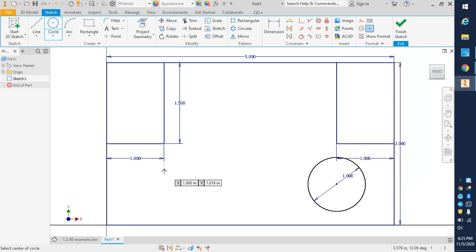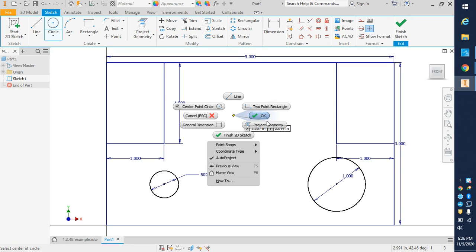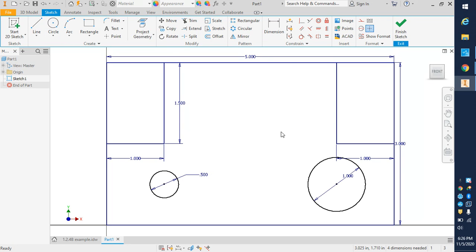All right, we're going to make one more over here. I want to share the same center as this one and this point, so I'll drag those down. Where those inferred points intersect, we can go ahead and click, move my mouse, and we're going to go 0.5 for the size of my circle there. And just like that, we are about done. Right click, OK, turns off my drawing tool. I'm ready to extrude. And watch what happens.